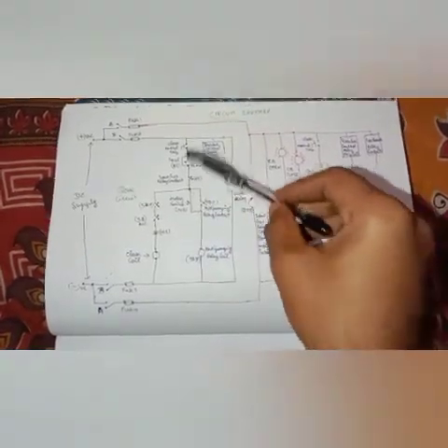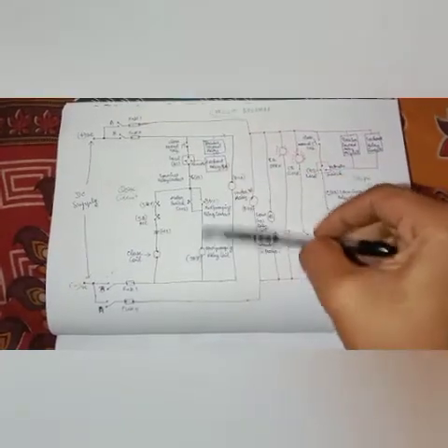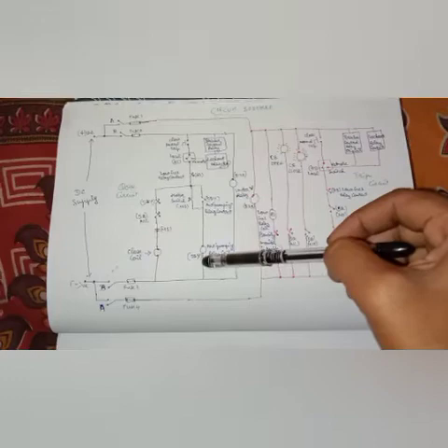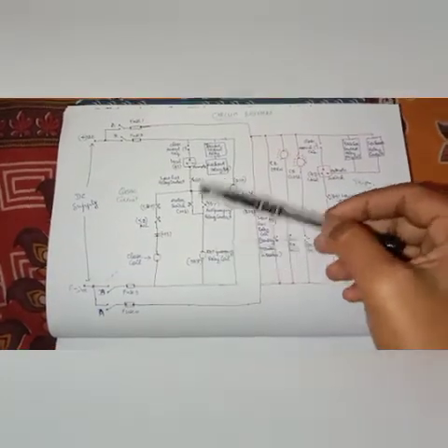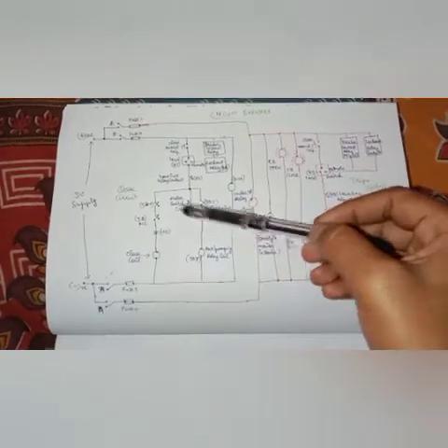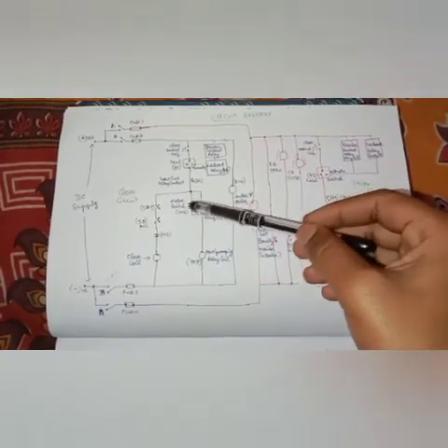This circuit will further move to your anti-pumping relays. So once the breaker is closed, a second time closing operation cannot be done.